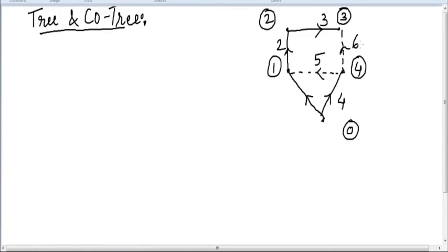So now just replace all the values of the self impedances which is given in the problem. One by one we are going to write the self impedances. So you can see from generator towards 1, the self impedance of this value is 0.1. So I will write here in bracket 0.1. Similarly, from generator to bus number 4, this value is also 0.1. So I will put 0.1.